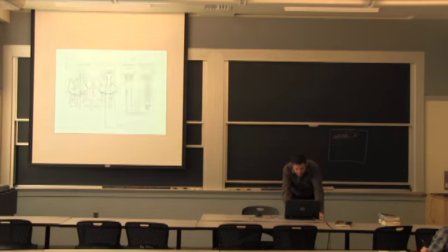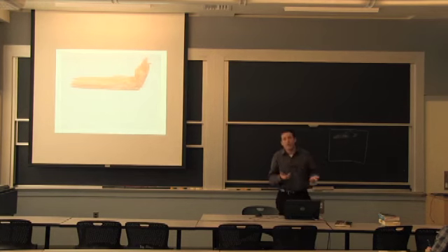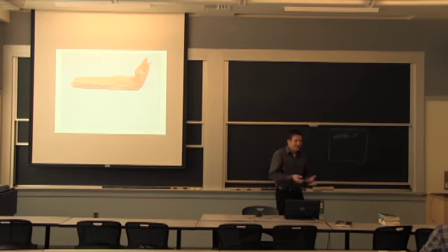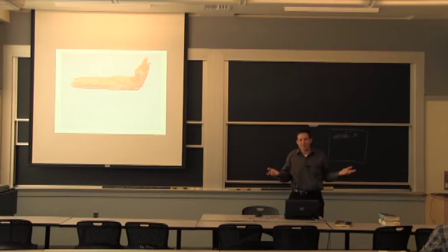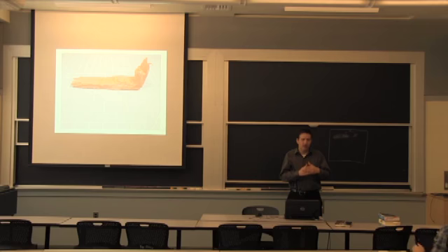One thing that was surprising to me, and the reason I put this up, I knew when I went into that tunnel that the beams were only about ½ an inch thick. So when I started seeing those pieces, I started really to wonder, is that beam going to fall? The answer is no, it's not really going to fall, because the rust expands by approximately a factor of 5 from being the metal to being the corroded, rusted steel.